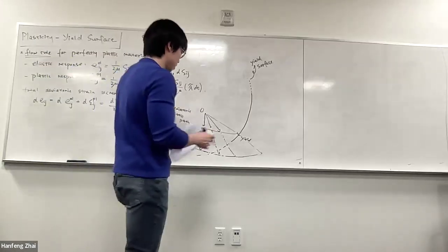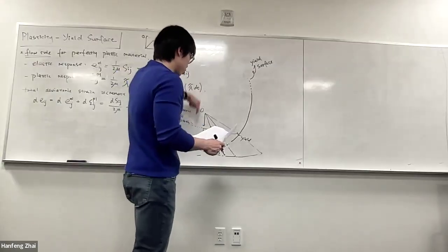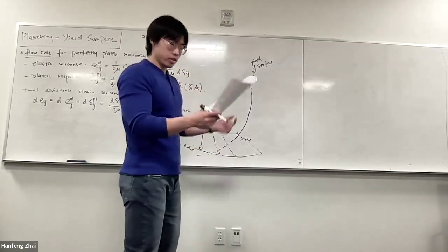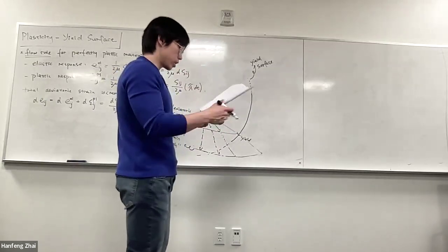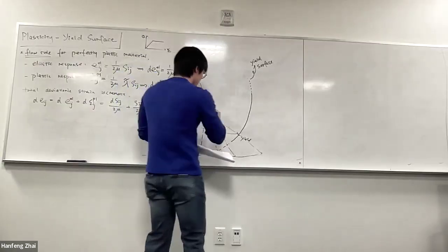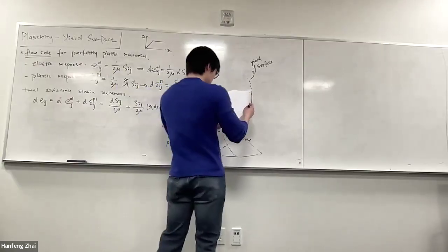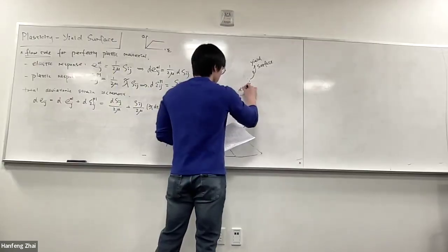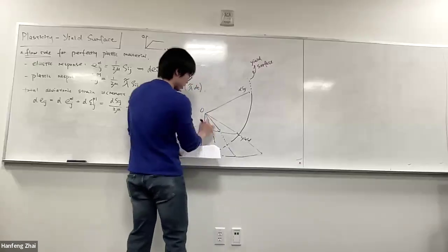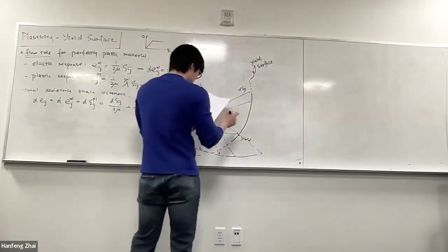And based on our calculus knowledge, if the stress follows a path and those are the stress components, then you can calculate the derivative and you know the direction of ds_ij, so those are s_ij, right? So the ds_ij, say it follows this direction. This is ds_ij, right? So accordingly, those stress components have their corresponding ds_ij, et cetera, et cetera.